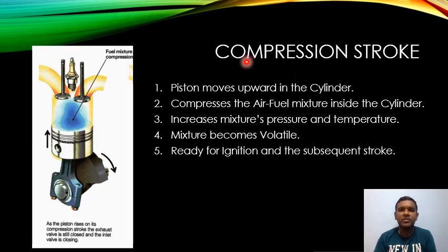Now, moving on to the second stroke, that is the compression stroke. Here the piston, which is at the bottom dead center, moves towards the top dead center. The intake valve, which was opened during the suction stroke, is closed during the compression stroke. When the piston moves up, there is already an air and fuel mixture present inside the cylinder, and the mixture inside the cylinder compresses.